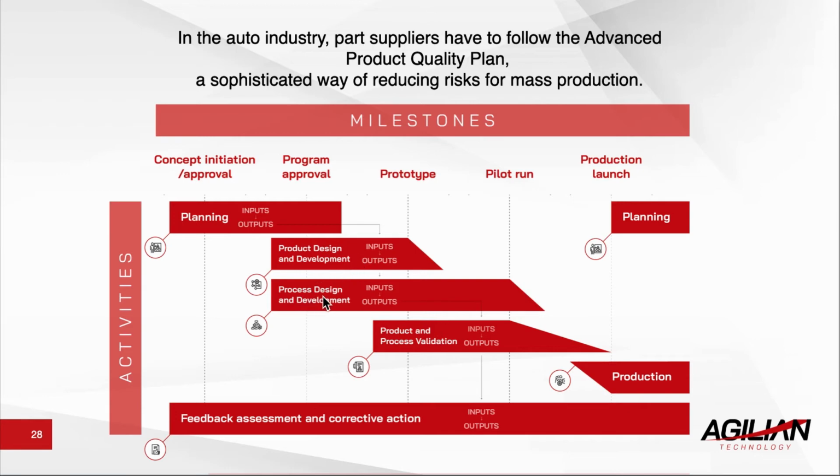But I can also start to think of the process design. Maybe making a silicone mold is also going to be very inexpensive and fast, but this will actually get me closer to the real hard steel mold for thermoplastics that I will end up using in mass production. So it's probably better to go with a silicone mold in this example, right?